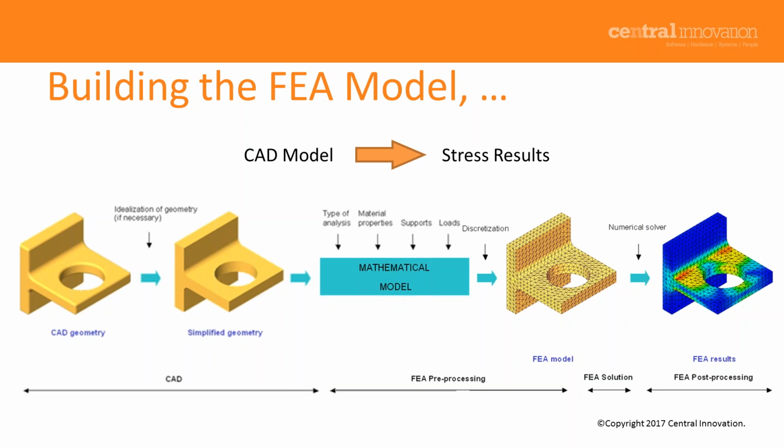Well, is it necessary? Is it cosmetic or functional? If it's functional, yes, we have to do it. If not, then simply ignore it. That's why from your original design, you always need a simplified CAD geometry. All unnecessary, non-functional features are going out in order to save time.